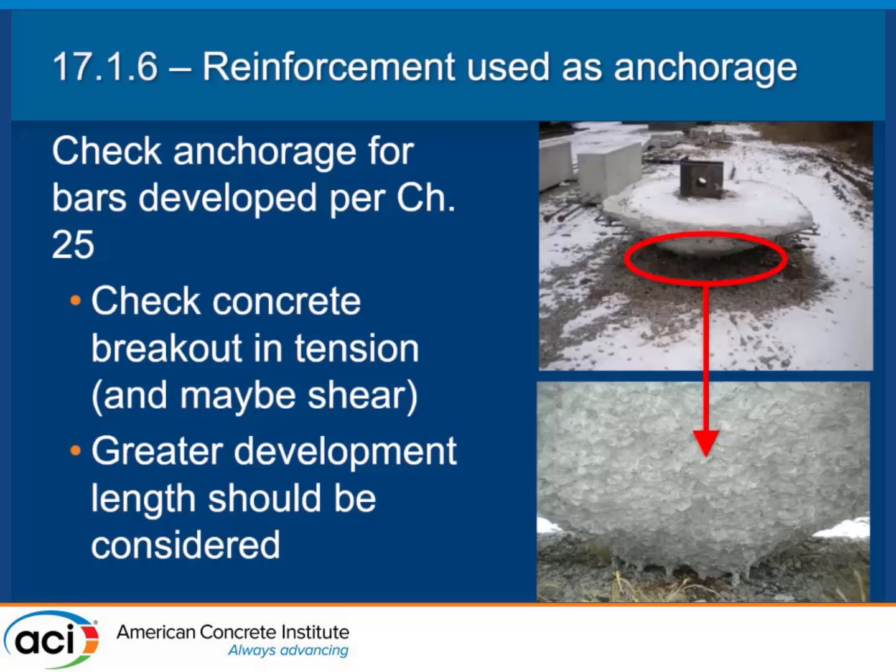One other thing I want to point out here is, okay, so this is a tension failure. I'm sure the load was probably more like this. But notice they did have a mat of steel in the top of their concrete. It is going in the other direction. It did absolutely nothing. So if you're worried about tension and you're putting steel perpendicular, you're getting nothing.